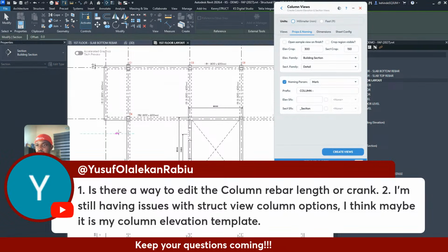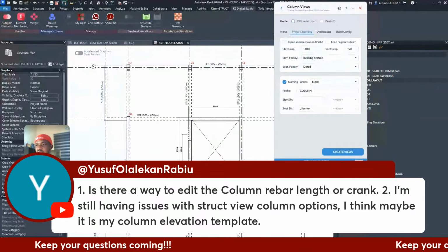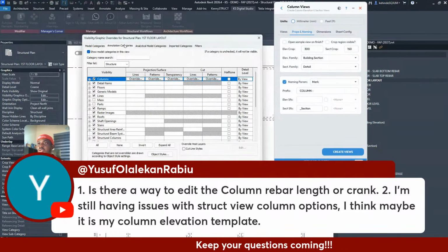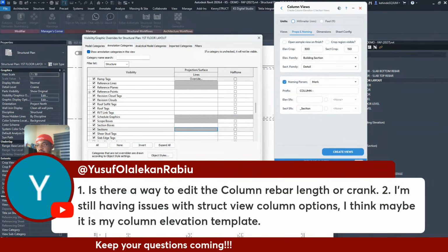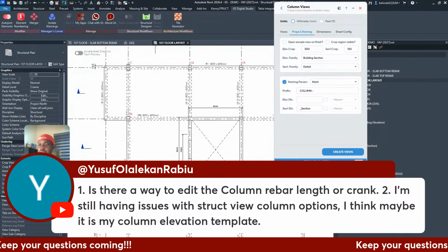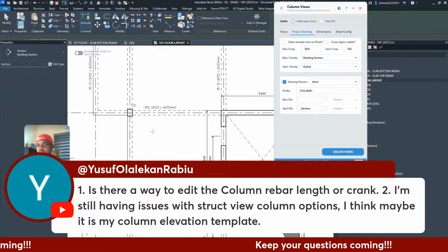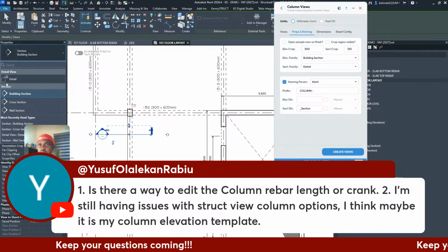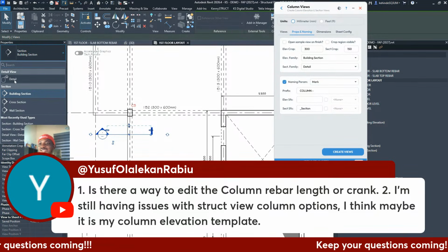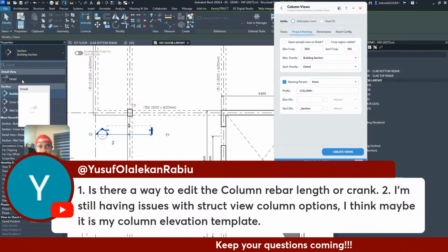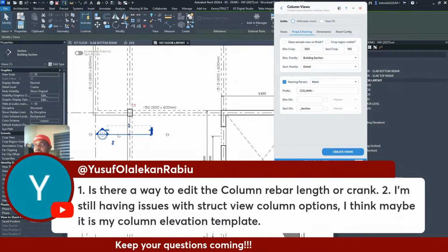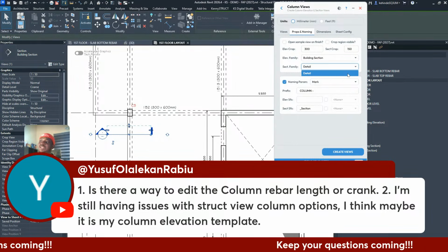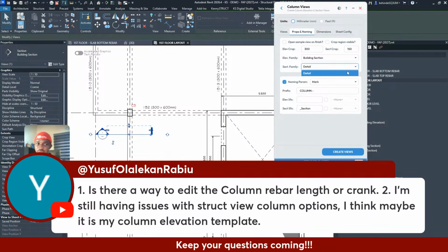This is a section. I'm going to turn on my sections here. So I draw a section. This is a section. You can see the two options when you click on it: this is a section, build a section, and this is a detail view. We use detail view for the section views, and for the elevation views we use a section family. So if you mistakenly pick section in this case, it might not work for you. That's how it works.